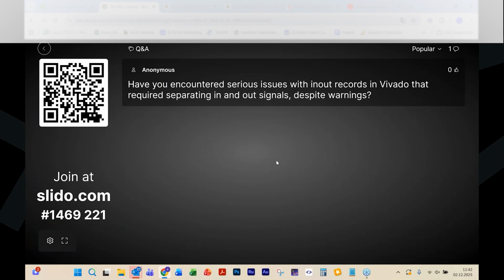Another one is that the synthesizer is a bit picky on figuring out ins and outs, to see later in synthesis that a single bit is just used as in and another bit is just used as out. Another thing you need to adhere to is when you create the signal, you need to initialize it with a vector of Z's, and this makes the handling overall quite complicated.